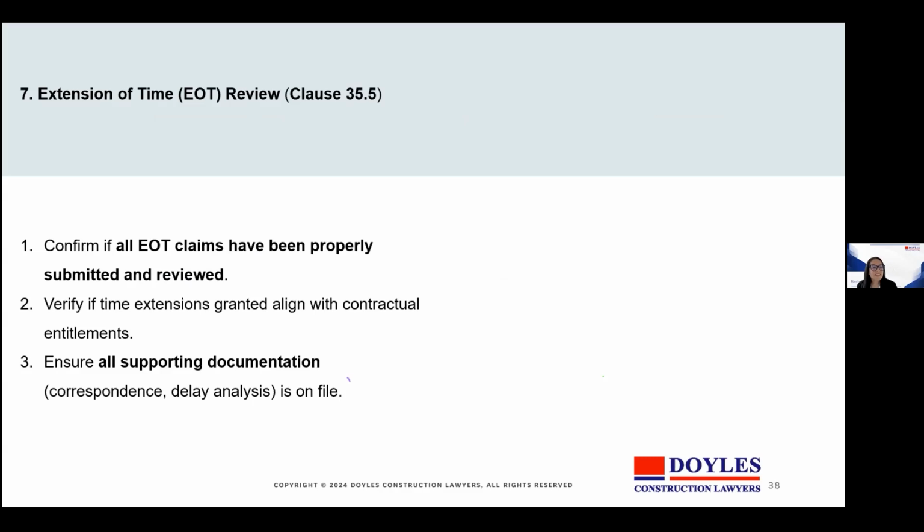Point 7, extensions of time, EOT review. So extensions of time entitlement depends on timely notice and supporting material. It's important that delay analysis is credible. So when you are going through the process, it's important that all EOT claims have been properly submitted and reviewed, that you verify extensions of time granted align with the contractual entitlements, and ensure all supporting documentation is on file, and that includes correspondence and delay analysis.